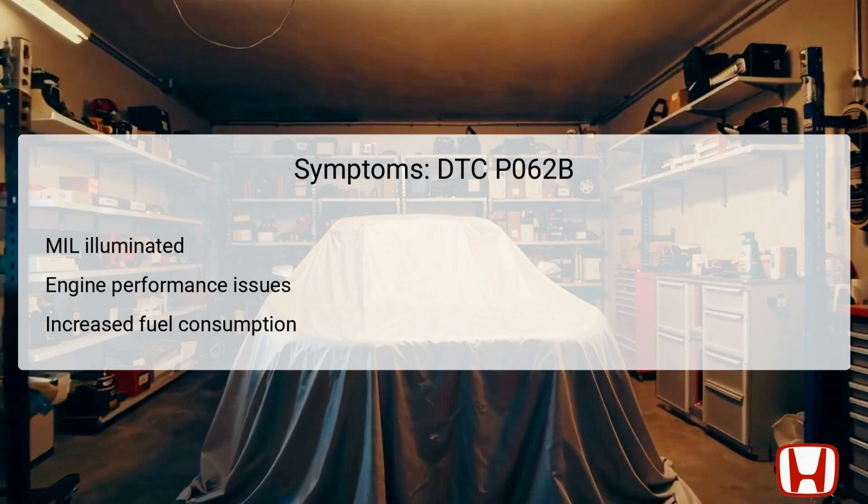Additionally, the vehicle may experience engine performance issues such as misfires, reduced acceleration, or rough idling due to improper fuel injection timing. As a result, it may also lead to increased fuel consumption as the system attempts to compensate for detected inefficiencies in fuel delivery. Recognizing these symptoms early on can facilitate quick diagnostics and repairs, minimizing further damage to the engine or associated systems.